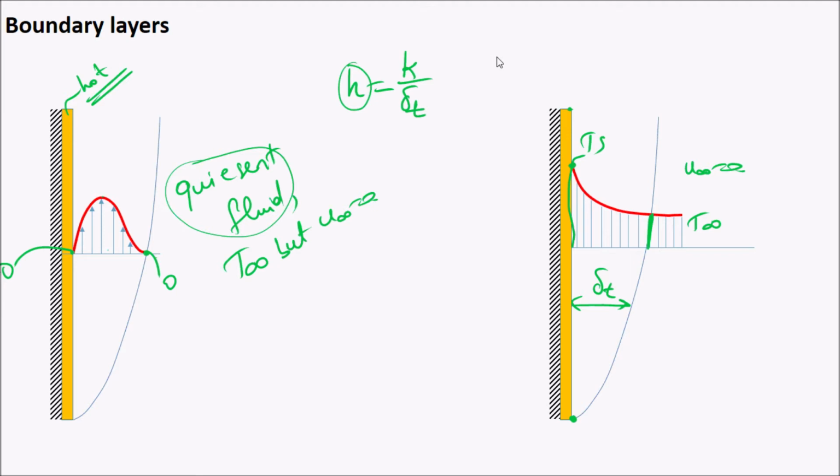The main difference between this one and the flat plate is that, if you remember, on external forced convection you again have the boundary layer growing, but there you have U at the surface as 0 and U infinity far away. Velocity increases from 0 to infinity. Here you have 0 at both sides, and velocity reaches a maximum and drops.